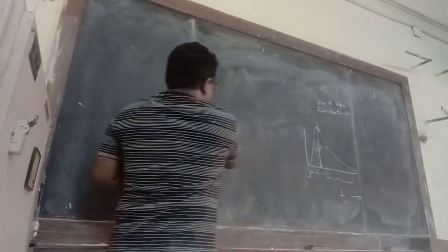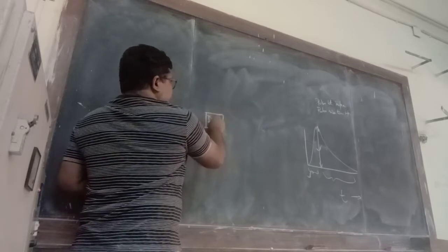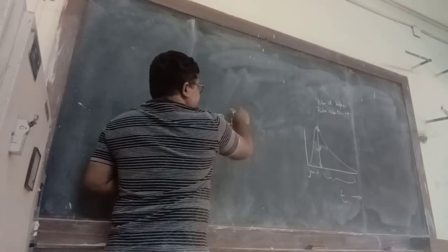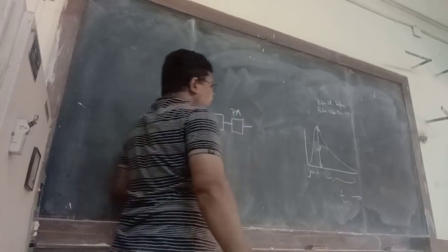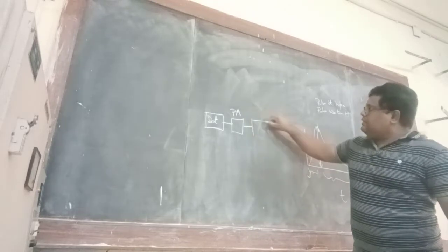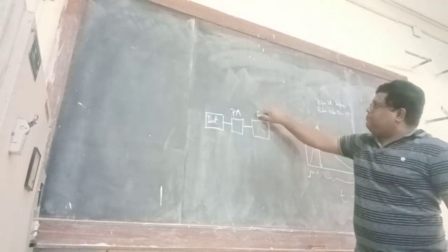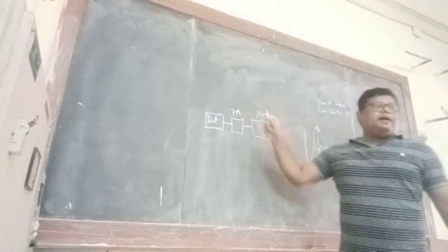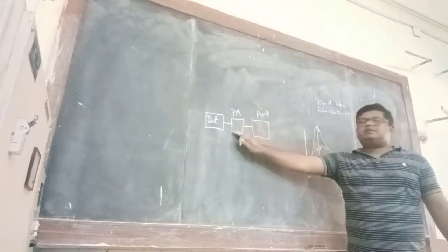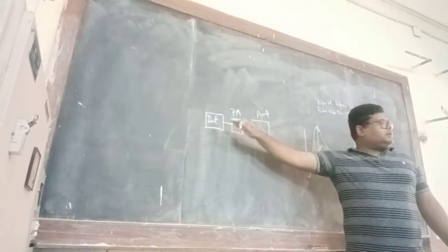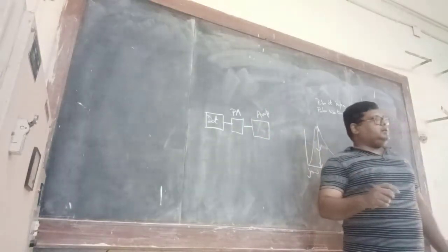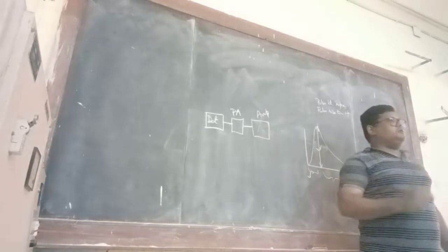Okay, so we have got the detector, and after that we have got something called the pre-amplifier. Let me first talk about it. Now what the pre-amplifier does is it reduces some of the noise associated with the detector pulse. Another very important thing is it does impedance matching.